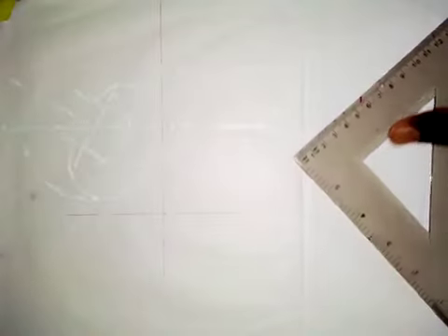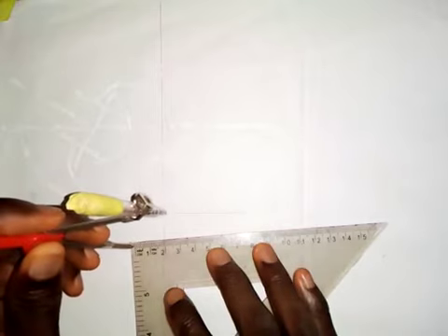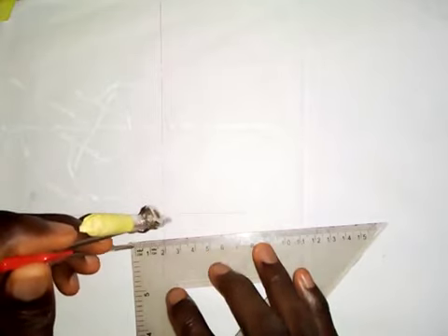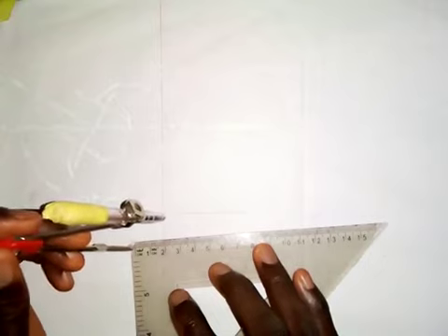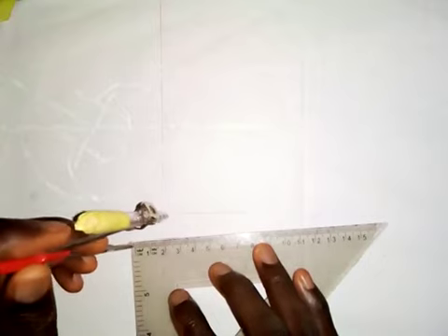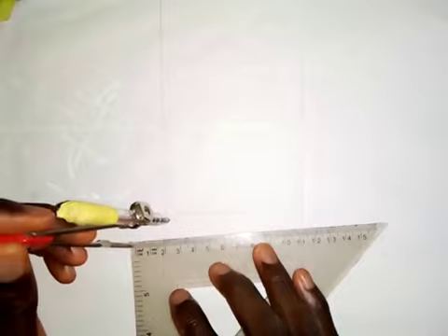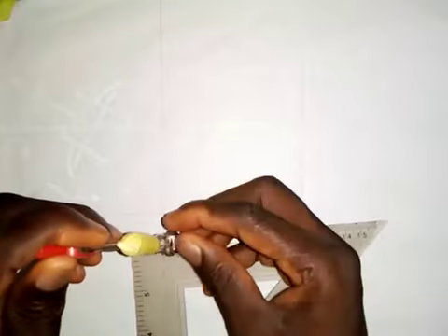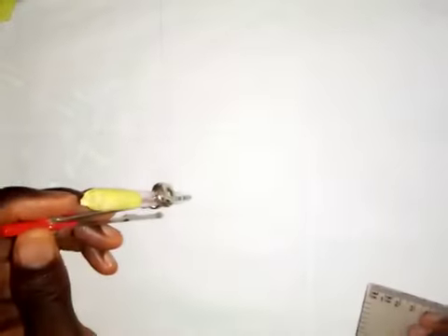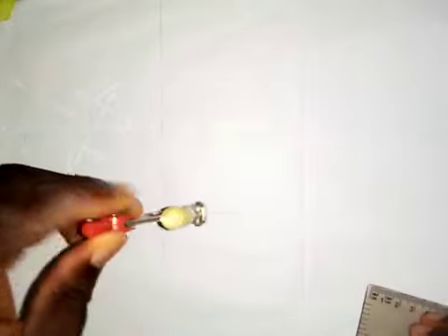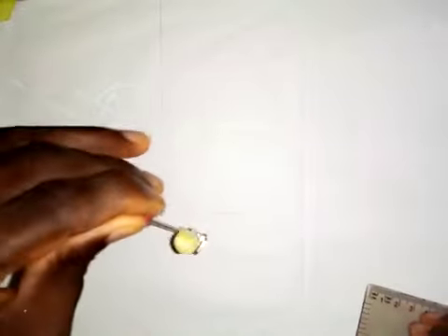All right, so if we multiply that distance across corner given to us, which is 25 millimeters, by 2, that will give us 50 millimeters. But we are still going to take a measurement of 25, because that distance across corner is for the diameter of the circle that we are to use to construct that hexagon. So the radius will be 25. So we take a measurement of 25 millimeters and we draw a circle like this.